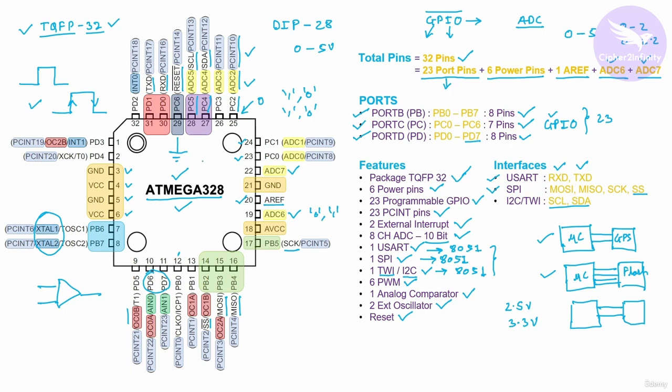It means that if you have programmed a code inside the microcontroller, then the controller will not execute that code, because you have connected this pin to ground. And when you release this pin and connect it to a logic high or VCC with the help of an appropriate value of resistor R, then the controller will not be in reset state, and it's going to execute the code which is programmed in this controller.